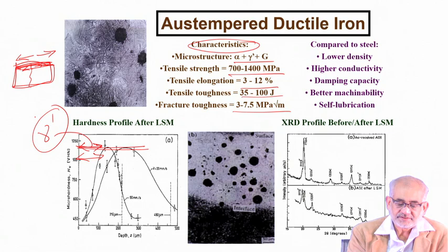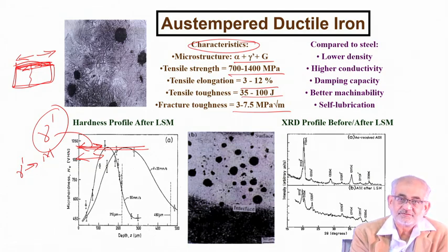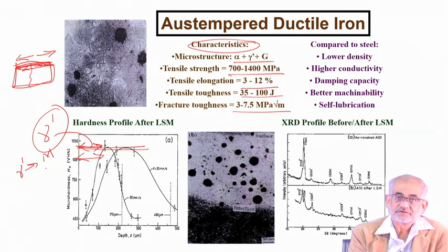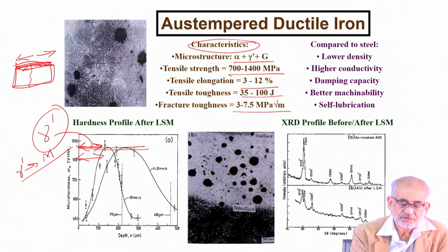We all are aware that there are several problems with retained austenite. First of all, this retained austenite, in the process of mechanical deformation, may undergo martensitic transformation, and that would mean expansion and creation of enormous stress within the solid matrix, leading to formation of microcracks. So these are hidden microcracks which may give in future and lead to catastrophic failure. So this is dangerous. We would rather like to avoid it.